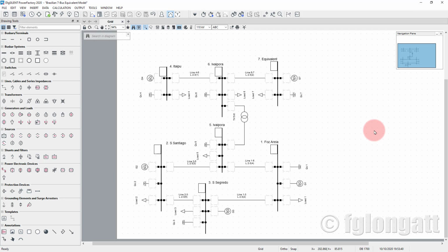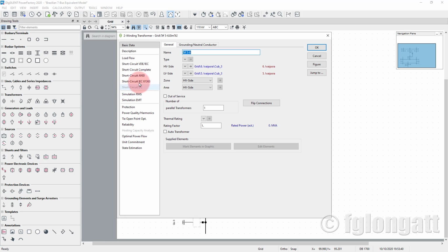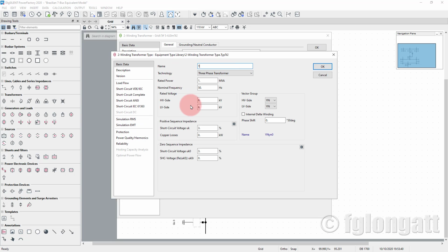One of the things that we need to do right now is define this transformer, and this transformer requires a new project type, and this will be the transformer TRX. Power 1060 here. The high voltage side should be 765, and the low voltage should be 500 kV, and in this case it is 3.9%.